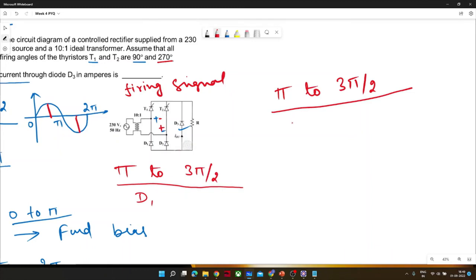semi-converter. If this freewheeling diode is not there and if some inductor is present in the circuit, then during turn on, this was being charged. Now during turn off, this charged energy would be discharged either through this diode or through D1 and T1, because T1 was on. I will explain more about this, but let me write here.